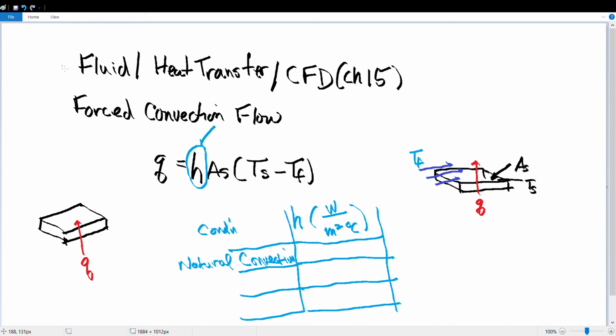And what's happening is that you don't have forced convection. Forced convection means that you have a fan or some kind of a pressure device, for example here on the right side, causing the fluid or air to flow. In this case, you just have standing air. So the air is going to travel this way, touch the hot surface, and start to go up due to buoyancy. So your air streamlines are going to look something like that. They basically touch the surface and go up.